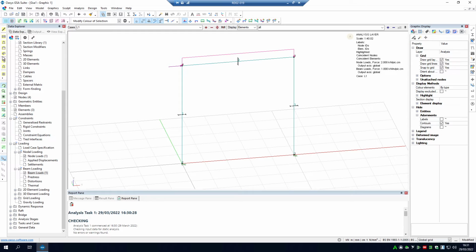So you want to go over to this far side over here, and you want to go down, select for annotation. Select for annotation is essentially, you go onto your model view, and you highlight a certain aspect, and it will tell you what that value is. This is for everything here. So all loads, all displacements, reactions, axial forces, shear forces, bending moments, and so on and so forth.